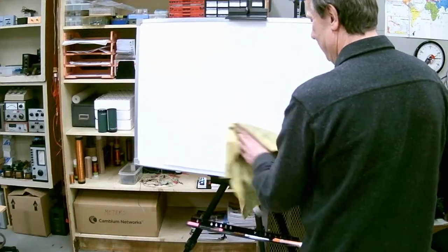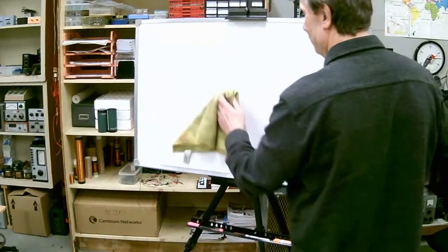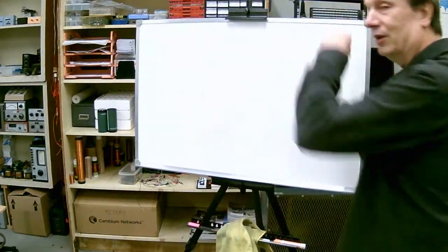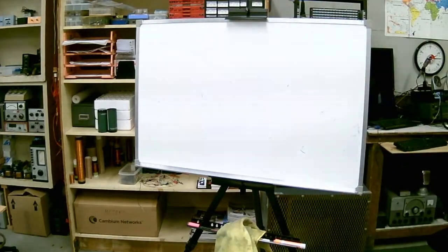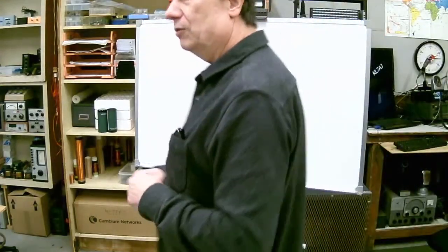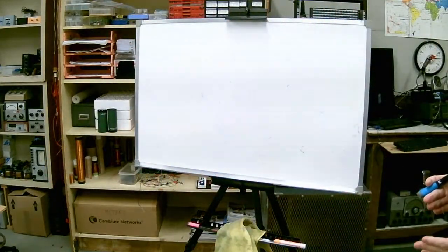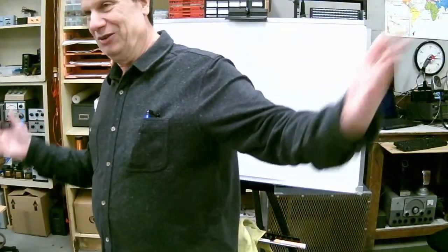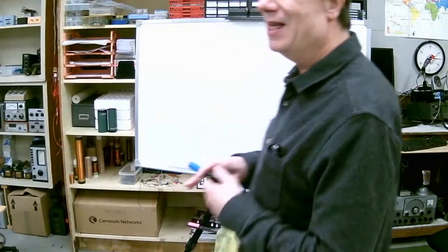And it's resonant, whereas that little guy up there is nowhere near self-resonant. He's way too small, so we have a capacitor across to tune it. It acts almost like a lumped constant circuit. So we have distributed voltage and current across the line there. We know that what happens here doesn't happen there because this is spaced away. It takes a while for a radio signal to get from point A to point B.